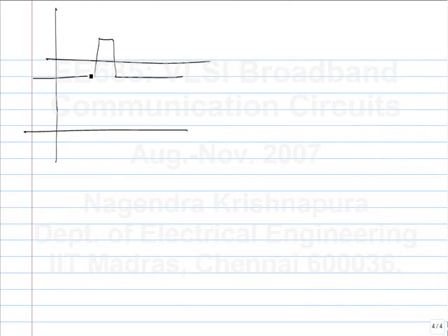So this is an ideal rectangle, although it doesn't look like that. And let's say we want to calculate the response of this, response to the signal of an RC circuit of some bandwidth. And we'll say that it has an initial condition of -1, and then it tries to go up and comes back to -1. What is this time? This is -1 and +1. So from this edge, what is this? No, it's not 90%. It's the zero crossing of the data. Yeah, it is going to half the amplitude, so that is 0.69 RC.